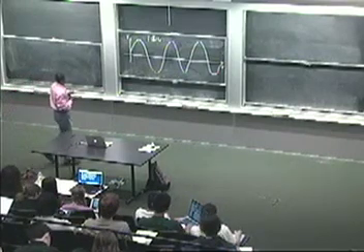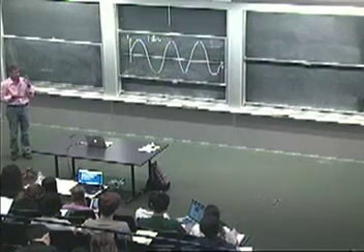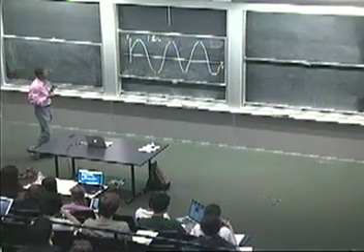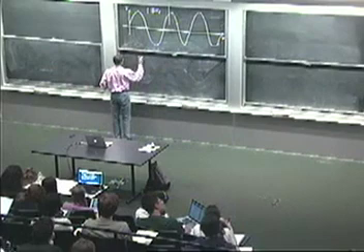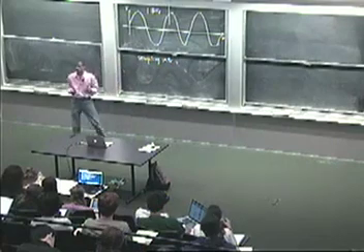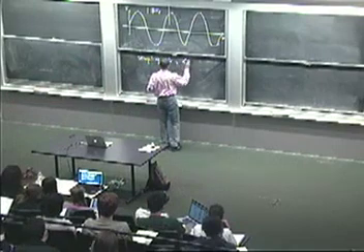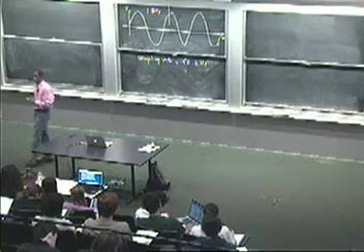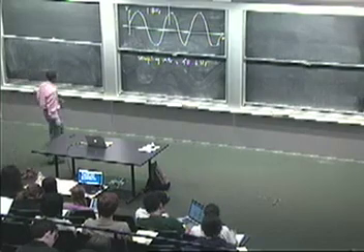What the receiver is capable of doing is, it's a digital receiver. So it's capable of receiving signals from the sound card at a certain number of samples per second. We're going to call that the sampling rate. We've used this term before. The sampling rate can be anything. By default, in this system, we've picked the highest possible sampling rate of 48 kilohertz. In some cases, you might have to yank it down. You might have to go as low as 8 kilohertz, but 48 kilohertz seems to work in the lab. It works on a bunch of machines that I've looked at.